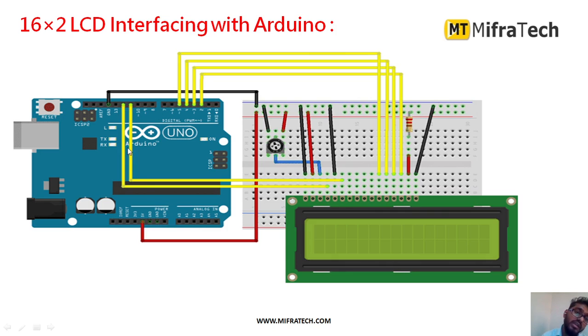As you can see, 11 is connected to enable pin, and 12 is connected to register select, and read or write I connected to ground. So enable is 11 and RS, register select, is pin number 12. Here I have also connected a potentiometer, this is in order to control the contrast. So this is the required connection in order to interface the 16x2 LCD display to Arduino.